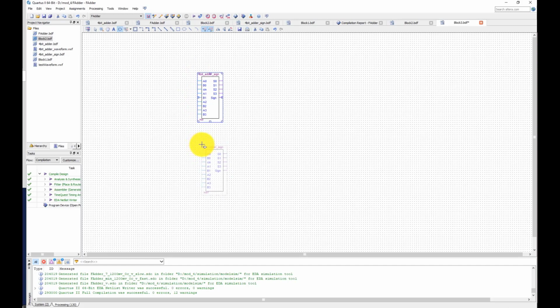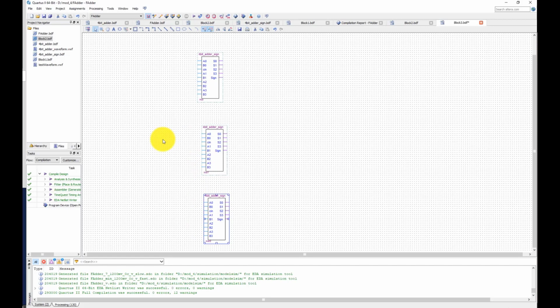So basically, if I want to do a 3-bit adder, in addition to my regular input, I have to do the following. The sign here, or the final carry out, I have to connect to carry in, all the time, and I have to label it like this, and the same thing here. Okay, perfect. You see that, guys?